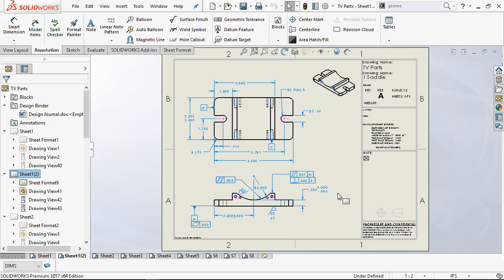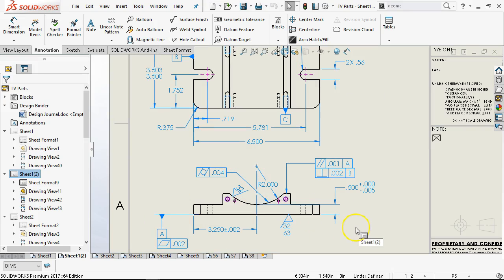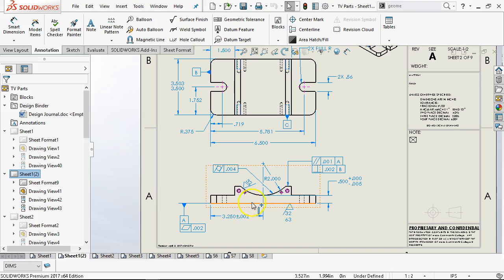You know, pick out the geometry that is critical and apply the feature control frames, apply your basic dimensions, and that is one that I did not put in there. So this one, as far as its position, this should be a basic dimension, and then somewhere a feature control frame related back to A for the position of the bottom of that cylinder.